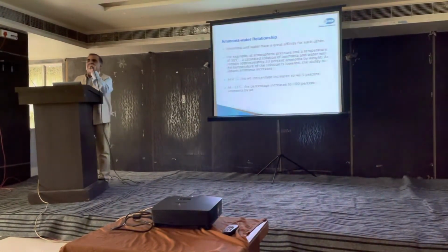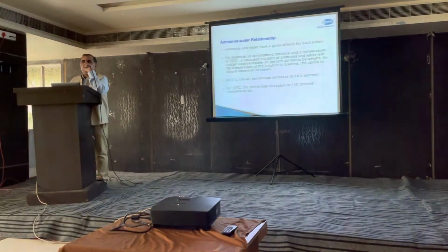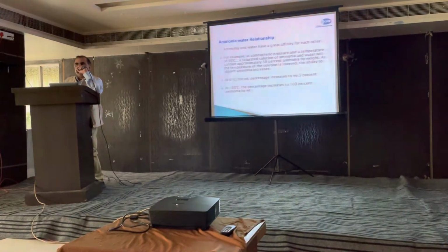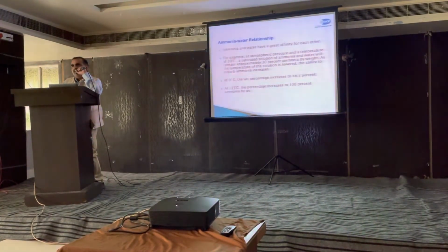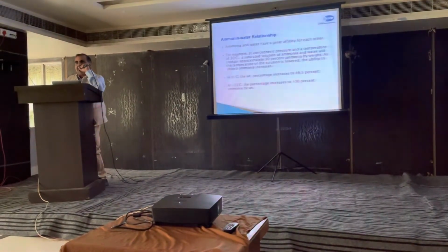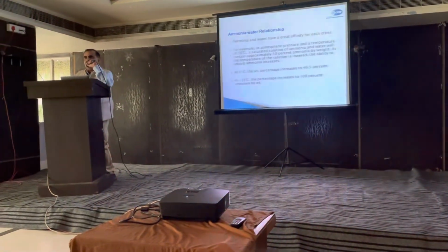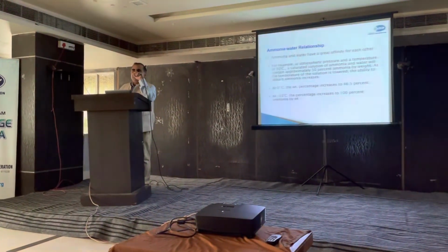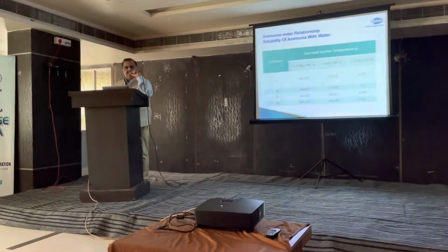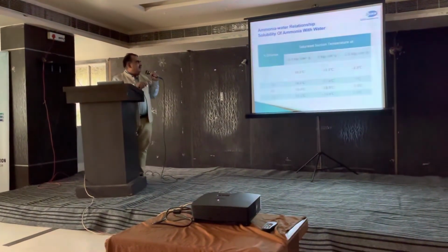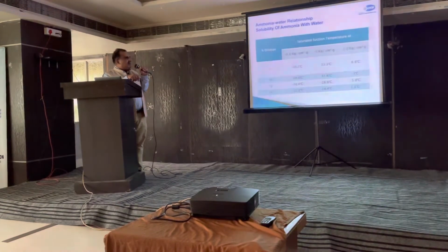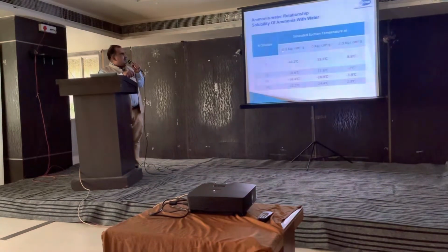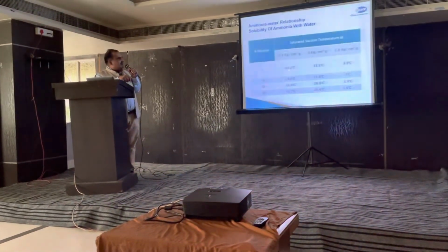If you remember, at the beginning of the presentation we saw the slide on purity of ammonia, where we said that we need 99.95% pure ammonia. And now, if water is there, then naturally the purity will not be there, and the pressure and temperature charts which we have shown will not be effective. This is the most important slide. Theoretically, if there is 0% water, or my ammonia is 99.95% pure, at minus 0.3 kg per centimeter square, I should get minus 40 degrees centigrade.